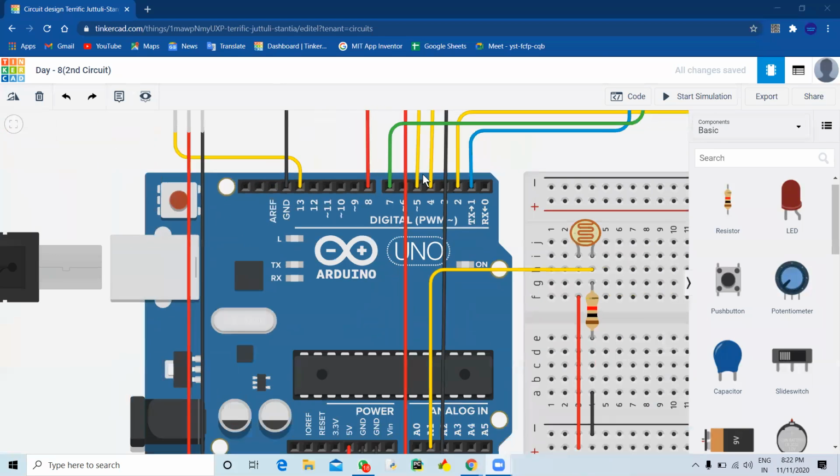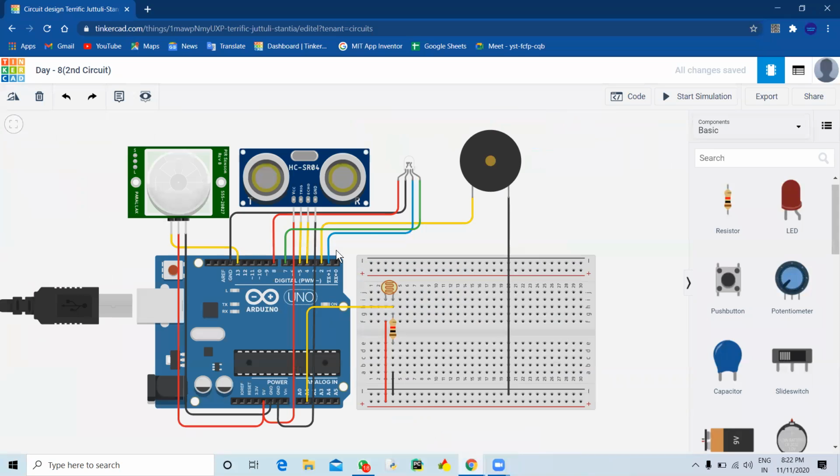And in these pins, you can control the amount of voltage. Like if we write LOW on digital pins, it's 0 volt, and if we write HIGH, then it's 5 volt. Only these two values we can control.